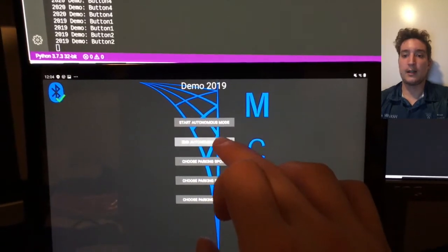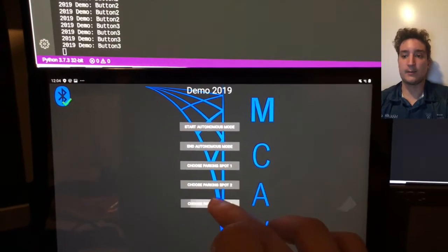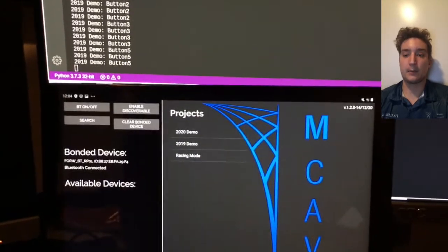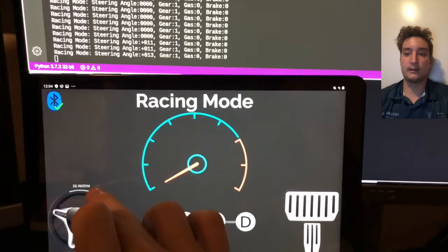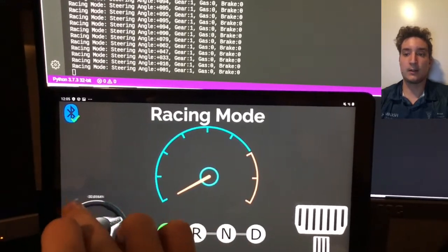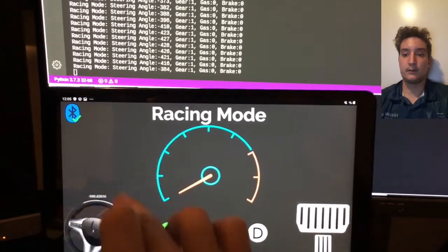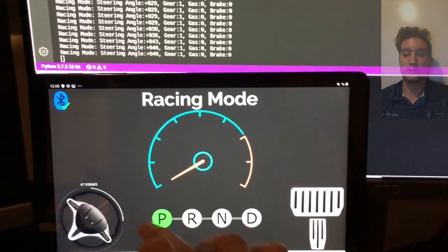The tablet communicates via Bluetooth to a Raspberry Pi that is mounted on the vehicle and is connected to the ROS network. Since the tablet-to-vehicle communication is wireless, the tablet can be used inside of the vehicle during tests or to show the state of the vehicle during tests to watchers at a base station.